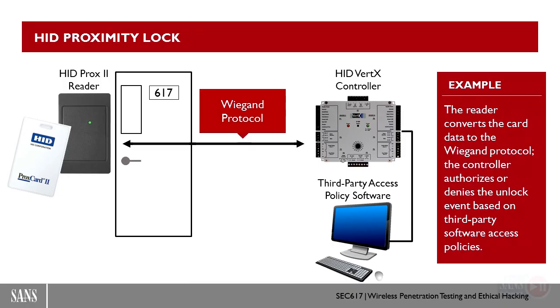Some of the tools that I've used here, there are two varieties. One is the ESP key, and the other one is the BLE key. They are very small circuit boards, one powered by battery, one powered by vampire power from the wire that is powering the reader. And it has the ability for us to punch it down on the wire without breaking the wire, effectively tapping the two transmission lines for the Wiegand protocol.